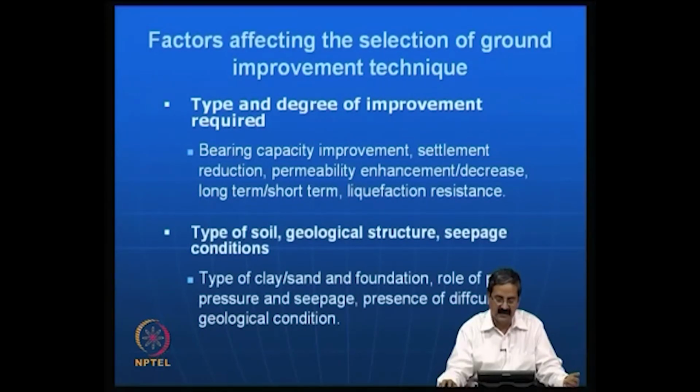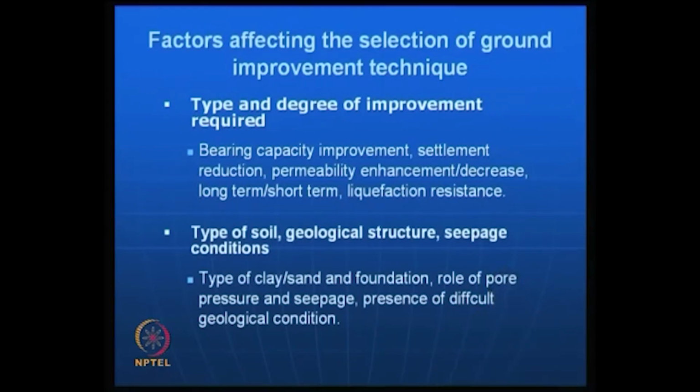Then the presence of difficult geological conditions, which I mentioned a few minutes back, such as karst deposits, which have a tendency to form holes, is another risky thing. So, the type of soil, geological structure, and seepage conditions influence the ground improvement technique choice.